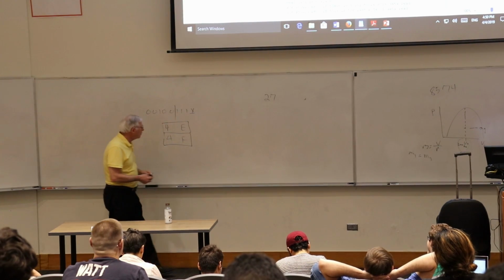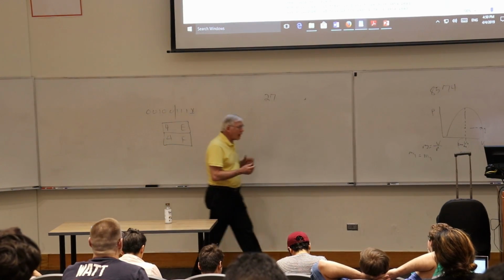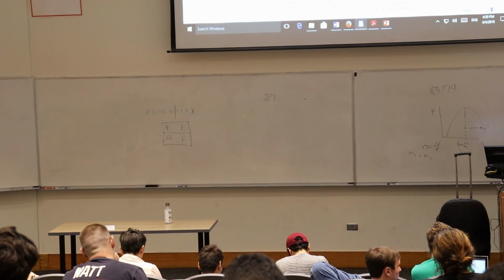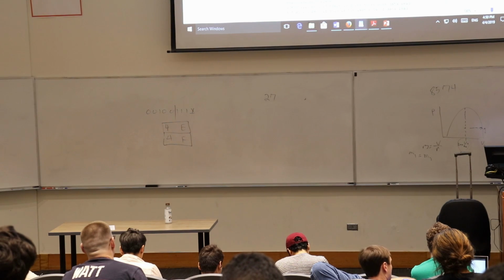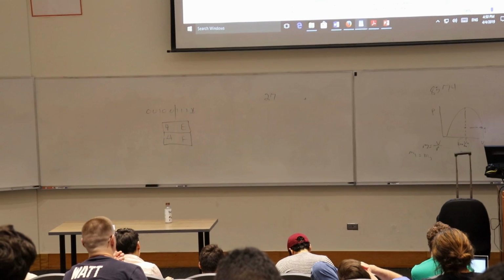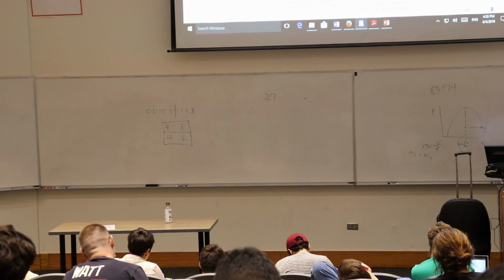So always remember that you have to be on the alert for whether you're getting the 7-bit unshifted address of the slave, or whether you're getting the shifted address with an appended read-write bit. And you have to read carefully.